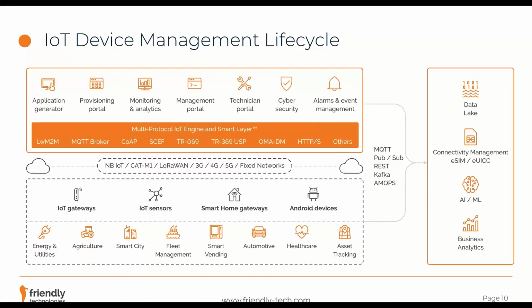So NB-IoT and Cat M1 support NIDD, and that would potentially be used in a module or device that requires ultra-long battery life and does not support a TCP/IP stack, where every bit of RAM, flash, and microprocessor power is of optimum need. So in a non-IP fashion, we're able to connect those devices through our management platform, including many of the IP-based protocols.